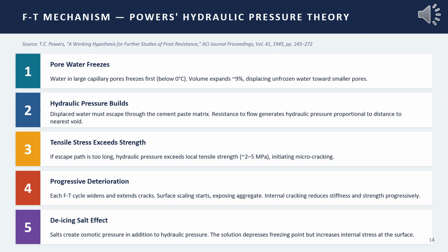Anyway, let's continue. So, step one is that as the temperature drops below 0 degrees Celsius, water in large capillary pores begins to freeze first. As ice forms, it expands 9%, displacing unfrozen water towards smaller pores and through the paste matrix.